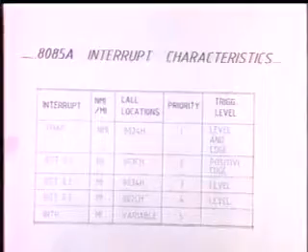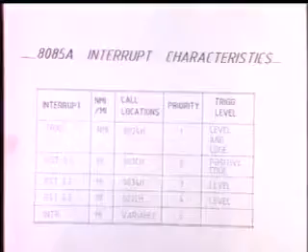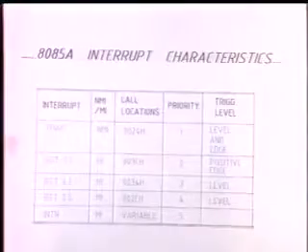So now we see that 8085A has got 5 external interrupts. The first one is TRAP, which is a non-maskable interrupt, and the remaining 4 are maskable interrupts, of which 3 are RST 7.5, 6.5, and 5.5, and the fourth one is INTR.